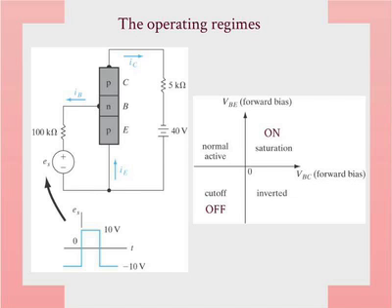Now, if you start putting signal into the collector, in other words, you put a small signal in here, and then your output will be here, but remember what we talked about in that situation, the amplification factor is less than 1. So yes, you do it for some special situations, and you don't care about amplification. Sometimes it's useful when you need exquisite signal fidelity and so on, because you can get very clear signals, low parasitics and things like that.